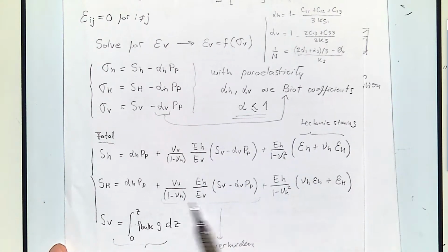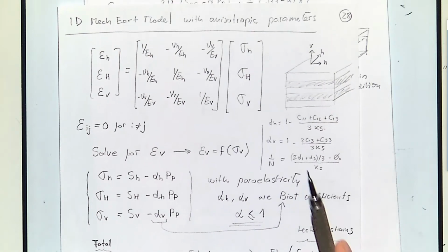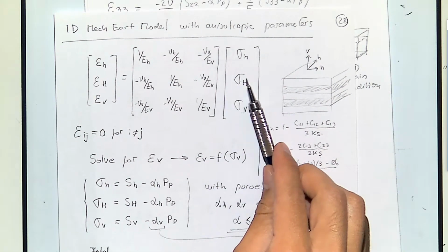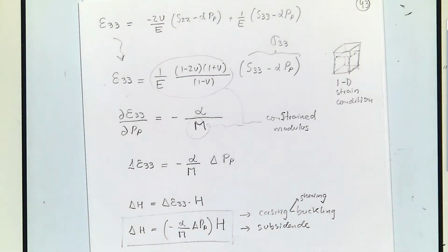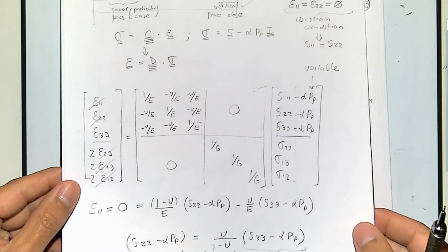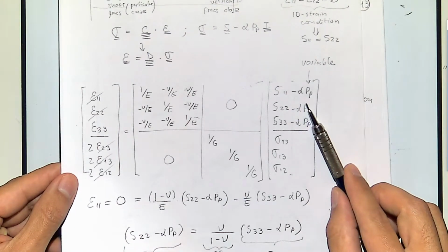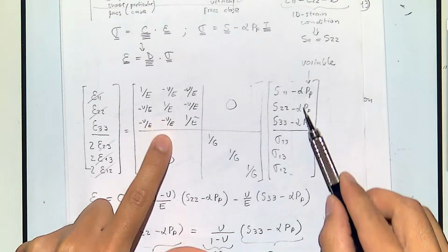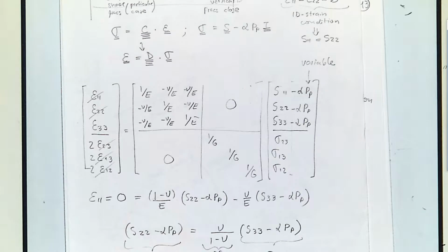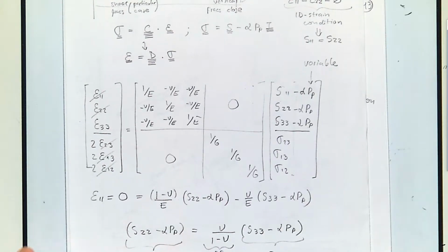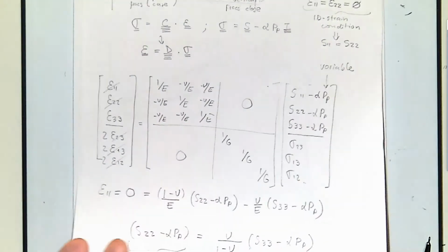And the derivation of these equations, again, it's very similar to this one, but now assuming that effective stress comes from the Biot effective stress, and it is exactly what we wrote in this problem, which is this one, but now you have to consider here an anisotropic matrix, an anisotropic Biot coefficient. You work with equations, and after 3 pages of derivations, you get to those equations. So if you don't believe me, you can try, and you will see that you'll get to that solution.